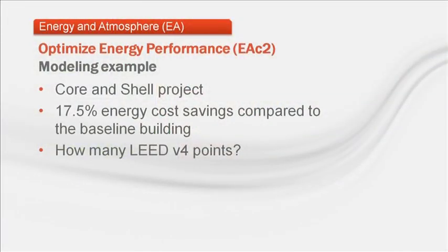Let's use this table to run through a quick example. For our example, the project is a core and shell office building, and the modeled energy cost savings compared to the baseline building is 17.5%. The question is, how many LEED v4 points can you earn?